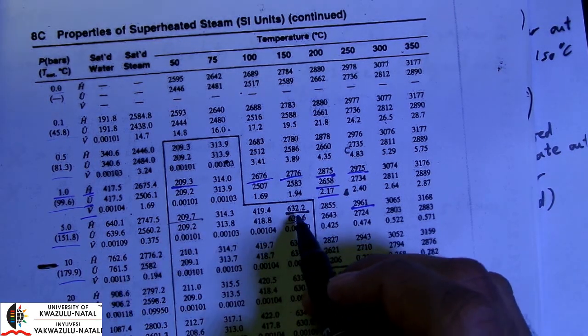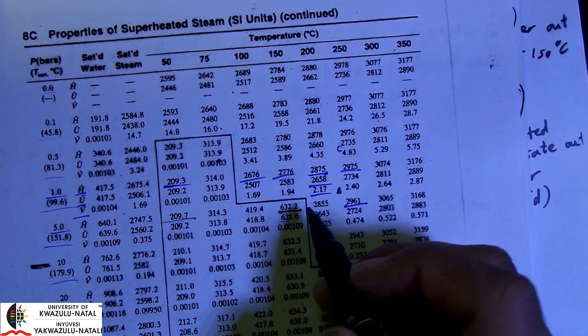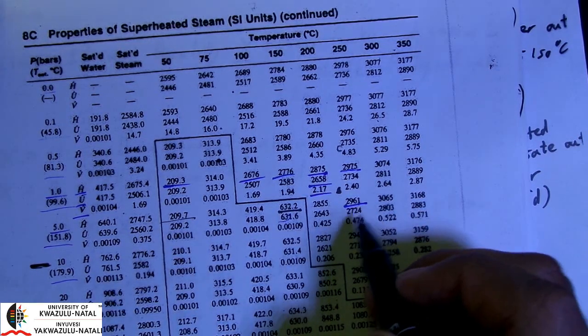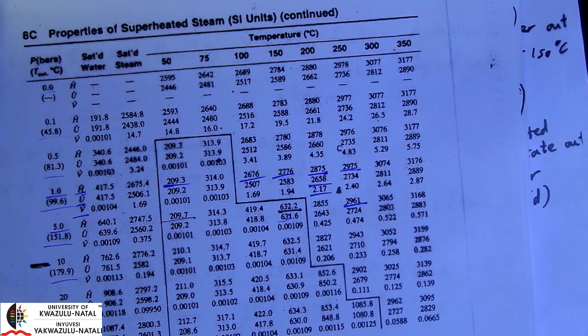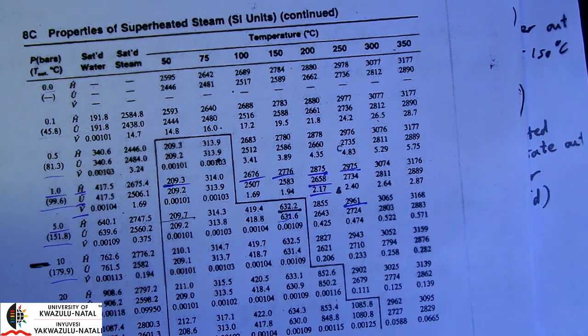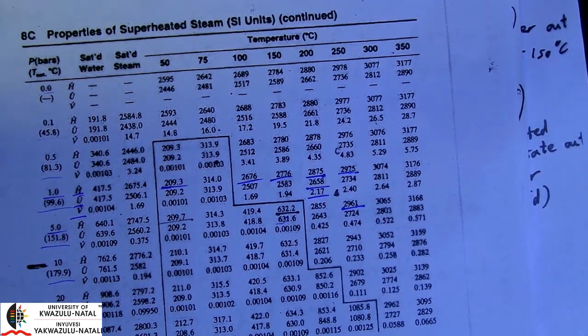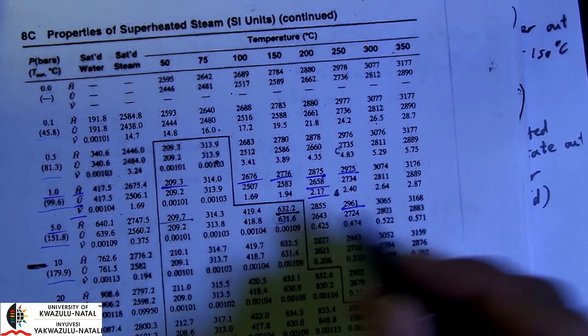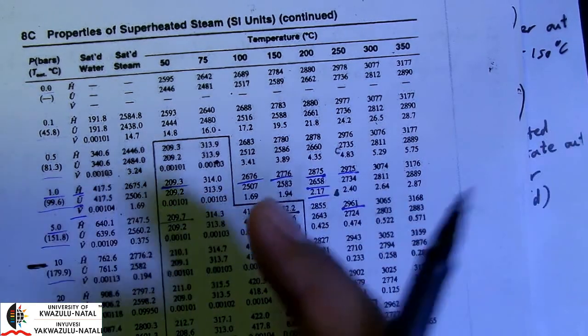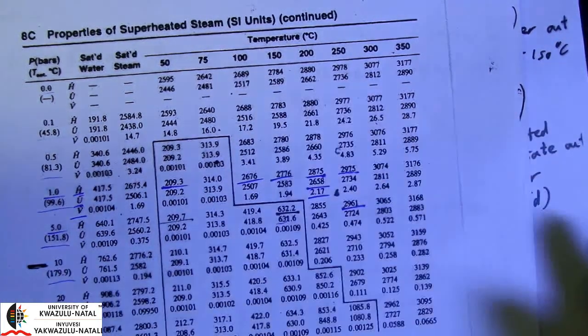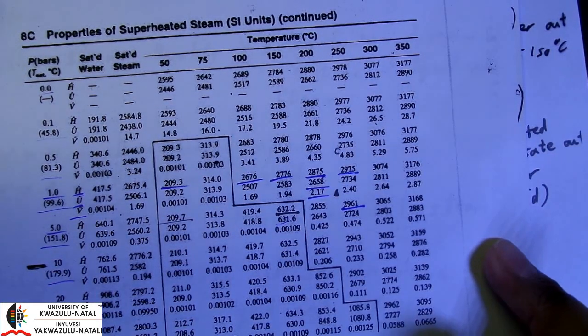Now if it vaporized, it wouldn't be a problem. We could simply look at our higher temperatures, whatever the temperature is, and perform the same calculation. Okay, and this is the convenience of using steam tables. We simply need to look at our input and our output. We don't have to consider our sensible heat, latent heat, and sensible heat in our gaseous phase separately.